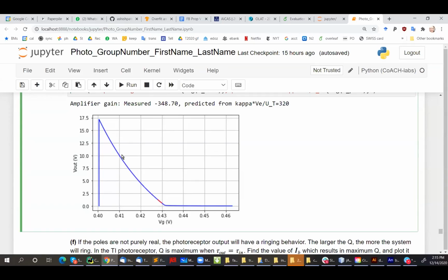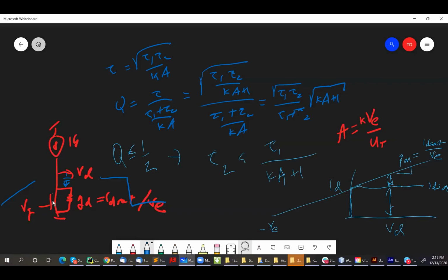So as the gate voltage gets higher and higher, of course, the output voltage goes down, right? As this gate voltage goes up and gets bigger than IB, then this output voltage will go down, right? If this saturation current gets bigger than IB, then what happens to this transistor? The saturation current is bigger than the bias current. So what must the output voltage do? It must go smaller and smaller. Does it go all the way to ground?